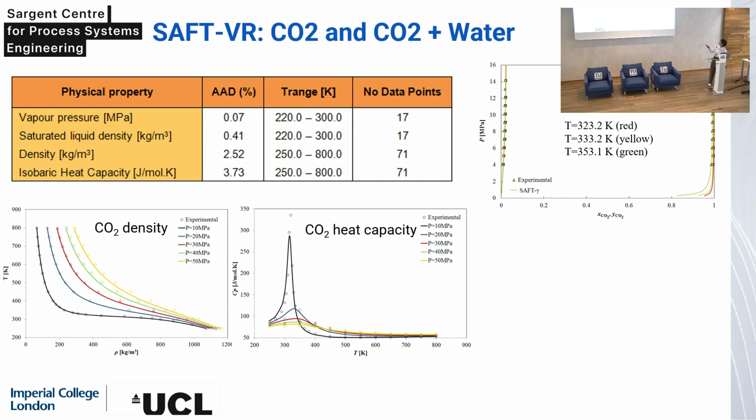that looks like this if we are at fixed temperature. So, 333, so these are your classic temperatures used in the process of CO2. We have on the left a phase rich in water. So this is pressure versus composition, and this is composition of CO2. So the right-hand side is pure CO2, the left-hand side is pure water. And what we have is a phase diagram that mostly corresponds to liquid-liquid separation.